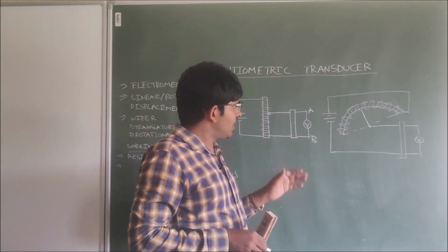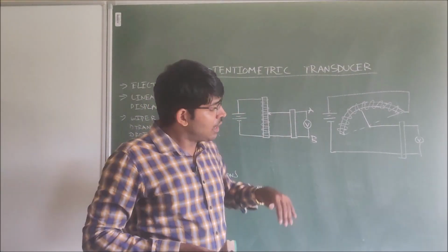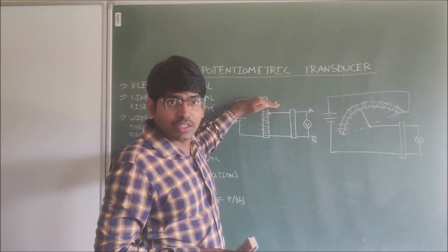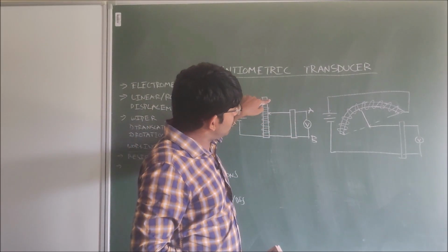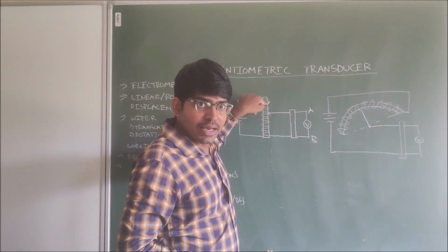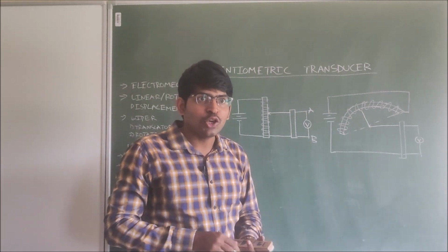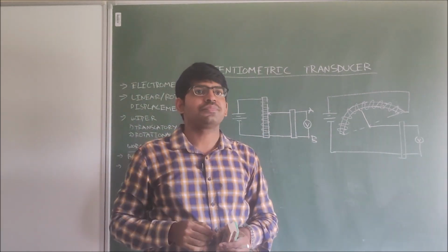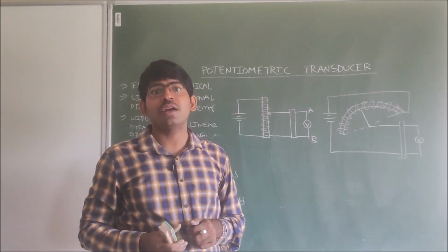Similarly, this we use for the linear displacement measurement. How much it is moving. Example, in your fuel tanks, if it is moving from this to this, then resistance changes and then voltage changes, your needle deflects. That's how you come to know, okay, petrol fuel is filling up.